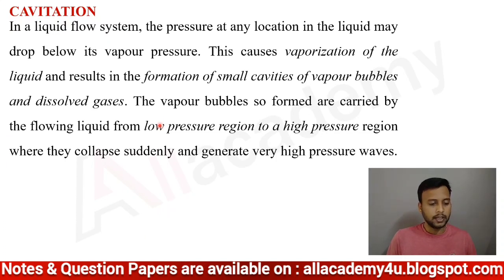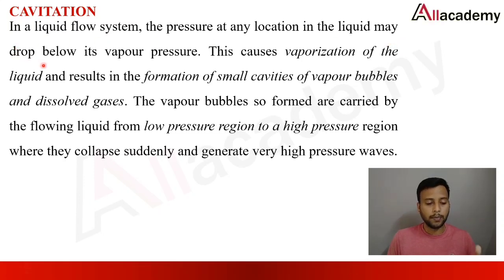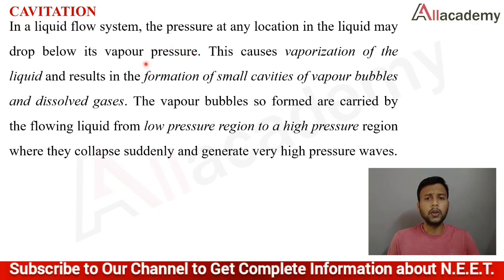In a liquid flow system, the pressure at any location in a liquid may drop below its vapor pressure. During the fluid flow, the pressure at any location may drop below the vapor pressure, and this causes the vaporization of the liquid and results in the formation of small cavities of vapor bubbles.